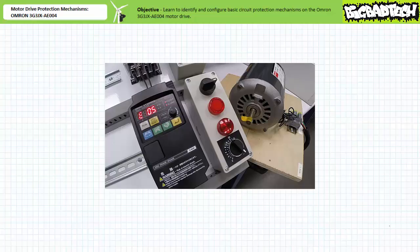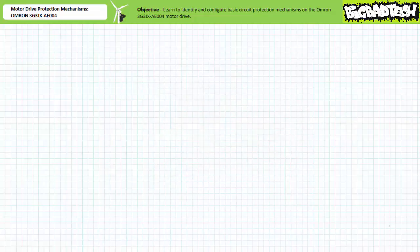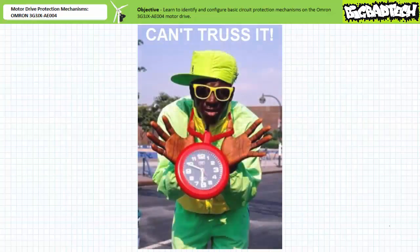A technician experiencing an overload trip must wait 10 seconds and then reset the drive to resume operation. Let's return protection parameter B012, electronic thermal level, back to the default state of 2.6 amps. That way we're not continually faulting out due to an early overload. By the way, the origin of frequent unwarranted overloads may simply be the fact that this drive's overload limit is set too low. Never assume for a moment someone isn't diddling with the equipment in your absence. Trust no one, least of all your lazy lab partner.